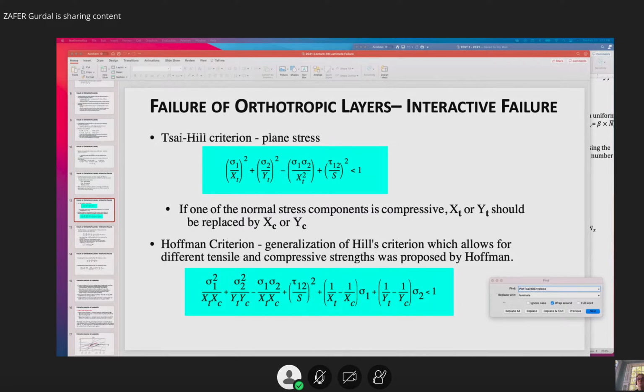Even if you have very few plies, as soon as you interchange the location of one ply, you're going to make a big difference in the D matrix. Whereas the A matrix is independent of the relative location of a ply through the thickness. That's why we are lumping in the homework problem,